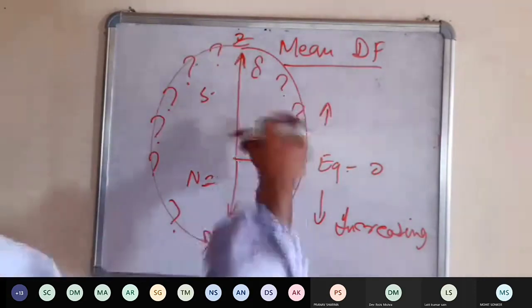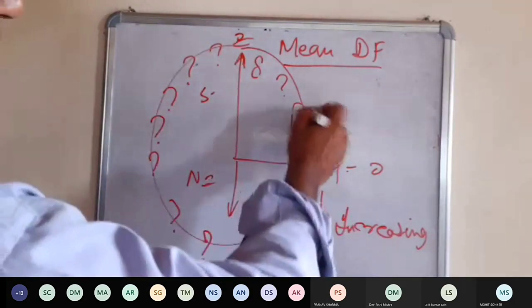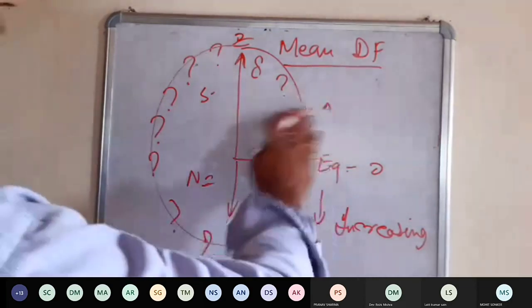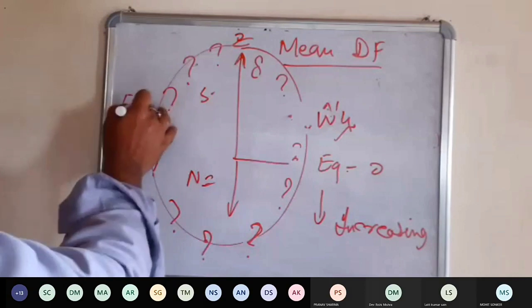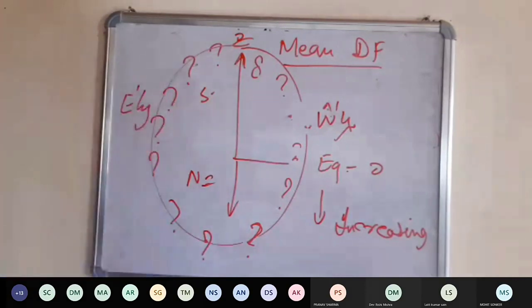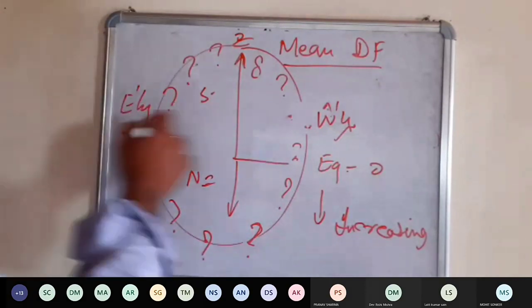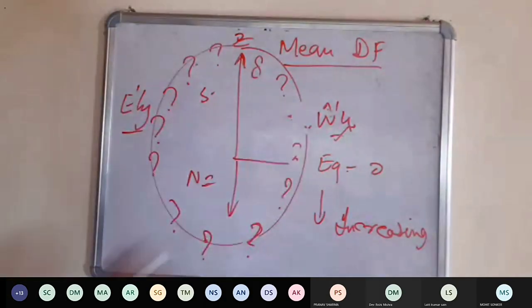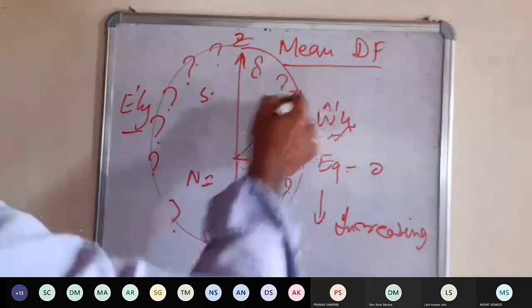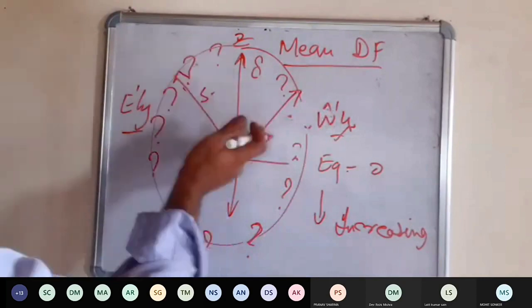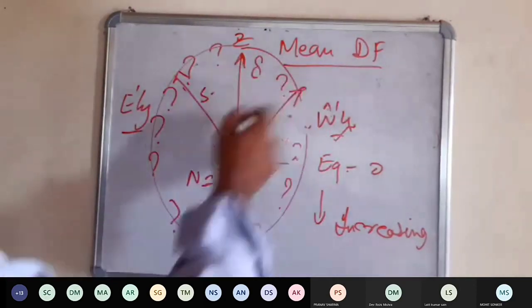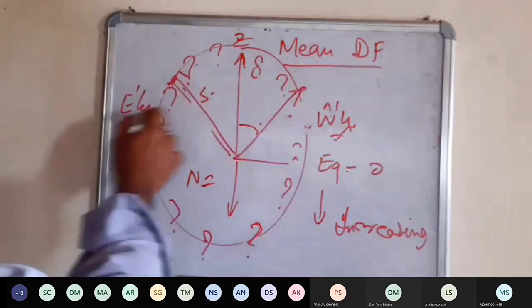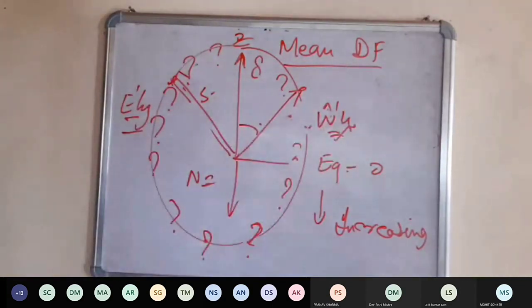In the previous case we have seen it is westerly on this side, easterly on the other side, and the deviation is equal and opposite on the same course in these two half circles. Whatever it is here, the same is there, easterly and westerly nullified.